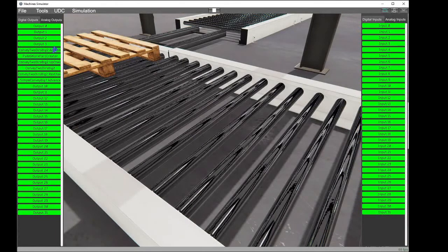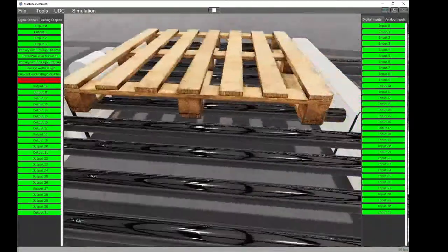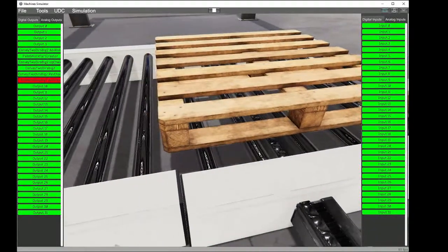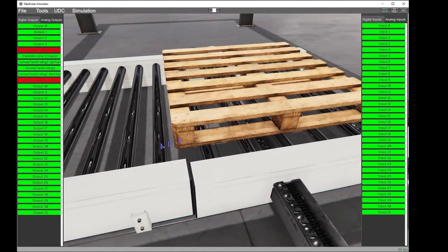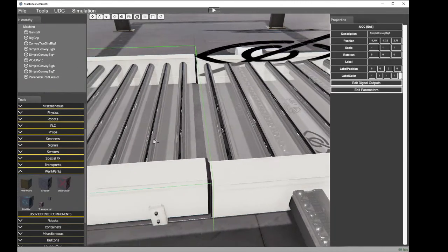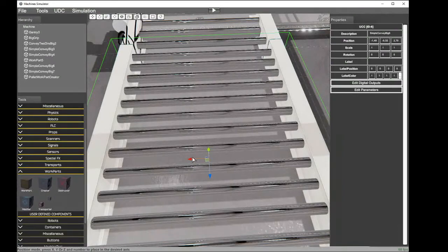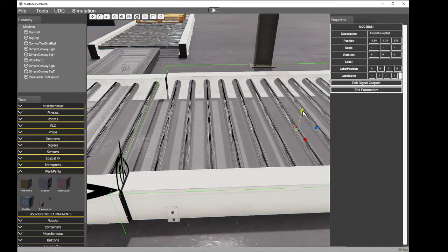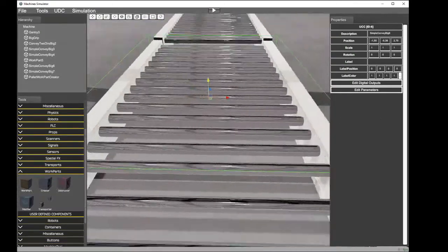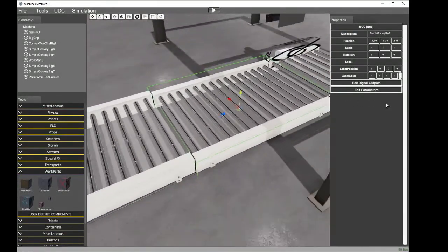And the output conveyor. But we see a problem, and this view is not correctly adjusted. Then there is a collision between the 2 conveyors. Then I need to adjust a little bit. Then I select the conveyor. I'm going to move in this sense, move a little bit down. Okay, perfect. I think it's okay.